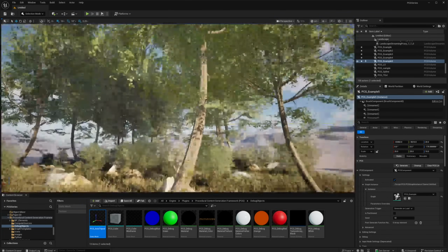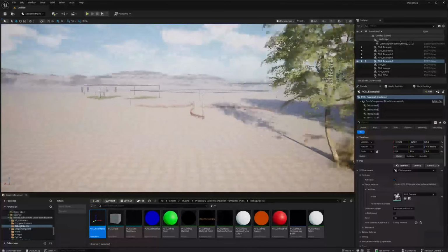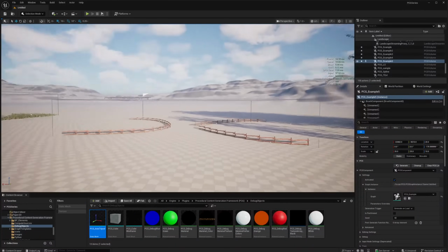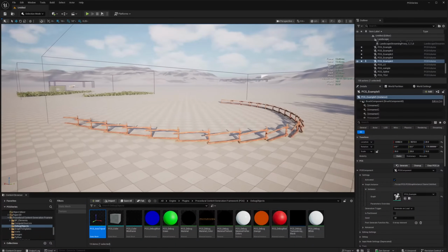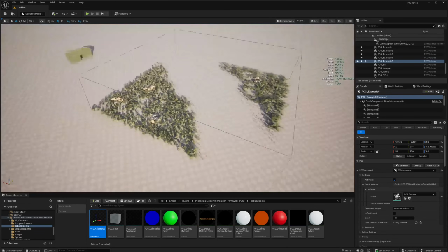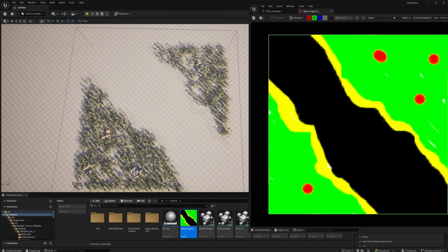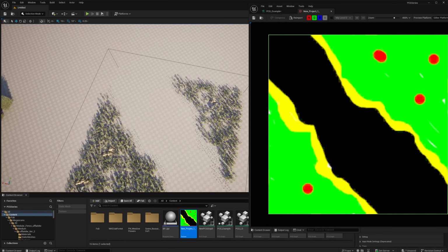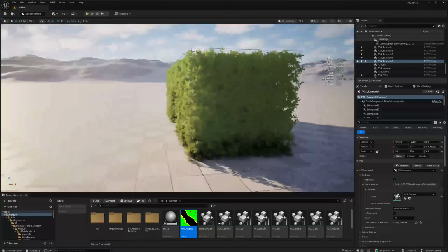Sampling lets you generate points based on another input. If you give it a shape, like a surface, curve, or volume, or a texture, it will give you back a list of procedurally created points. Each sampling method has its own rules, as they often do different styles of generation. So let's see what the different samplers are and when to use them.